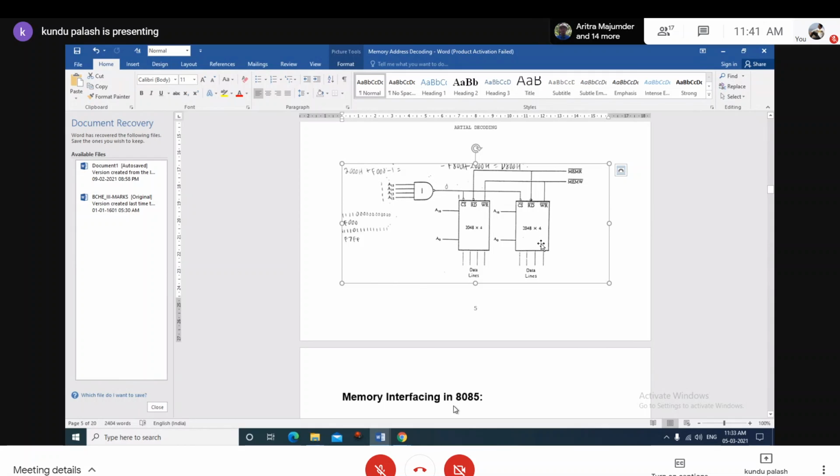The blocks will be selected for the physical address range of F000 to F7FF, or there will be another duplicate address range up to FFFF. That means if A11 is 0, the top address is F7FF. But if we assume A11 is high, then the top address will be FFFF.